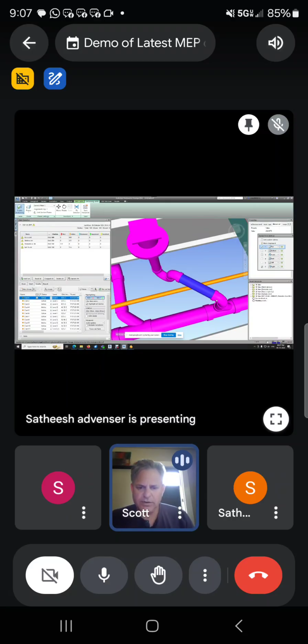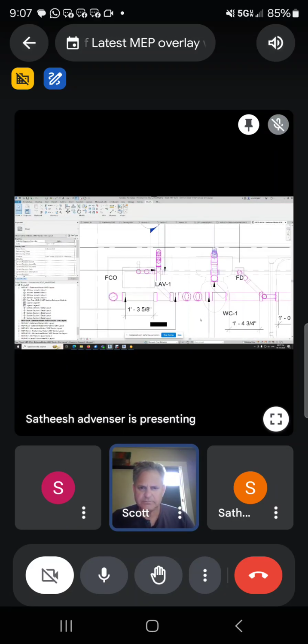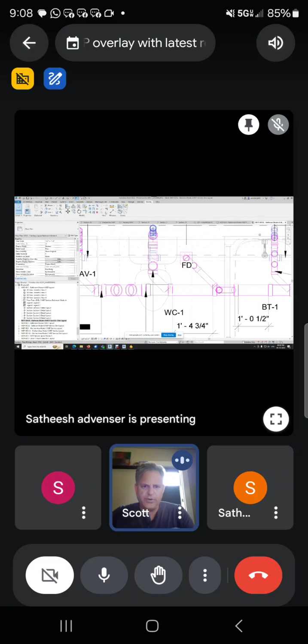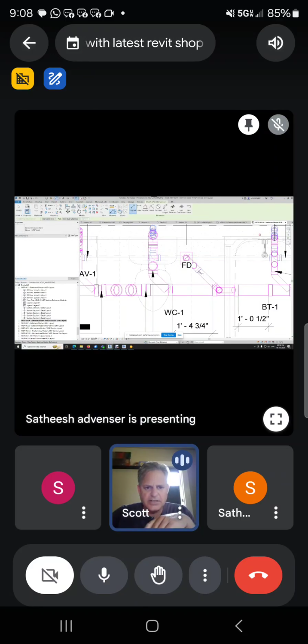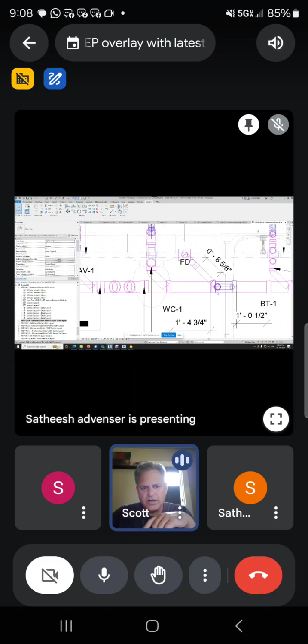So along with your drawings, can you go to a 2D floor plan of that area? Yeah, this area. You've got all these measurements, this is just incredible work. But really what I would like to see is, let's talk right where that FD is coming up. You've got the flow, you've got the P-trap. Yeah, this is the pit. So a center line of that coming off of a wall or an outer line would be perfect.